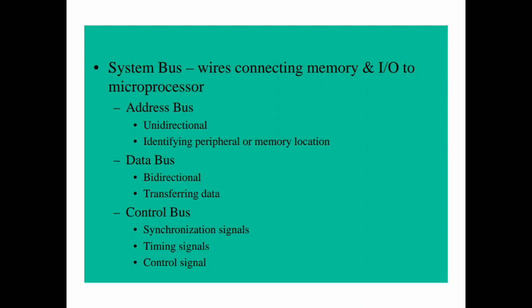So the address bus carries the address of a memory location or input-output device that the CPU wants to access. When an address is sent by the CPU, all devices connected to the CPU through the address bus receive this address, but only that device will respond which has also received chip-enable signal from the CPU. Thus, address bus is a unidirectional bus.